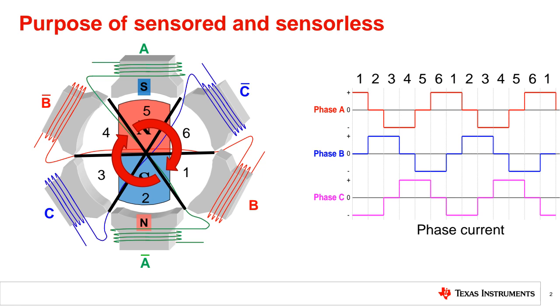In the typical motor equation, we have, for example, the Q-axis voltage, VQ, equal to resistance times armature current plus inductance of phase winding times di/dt, the derivative of current, plus back EMF.